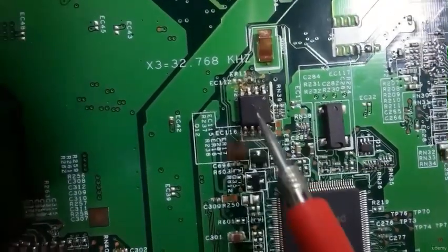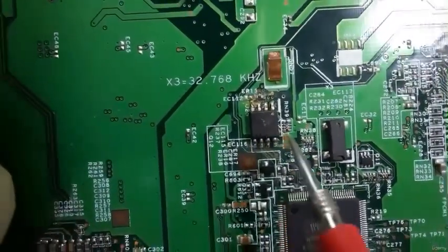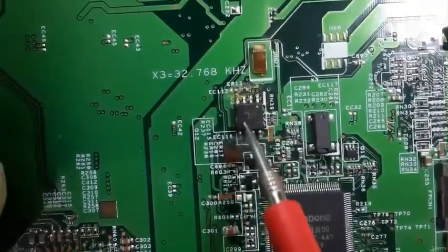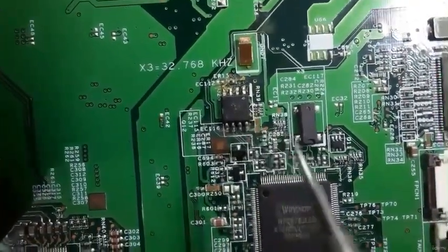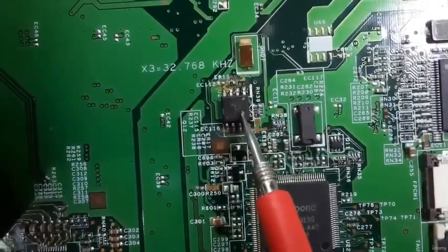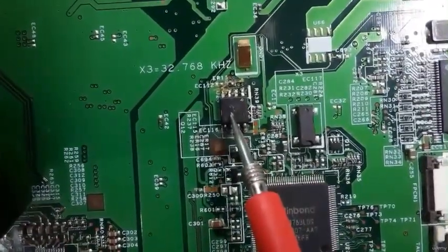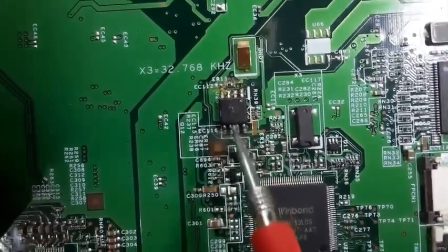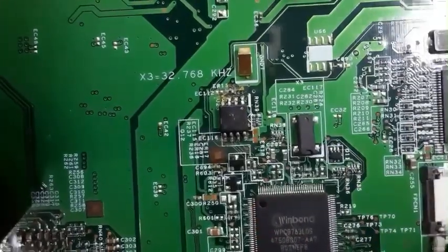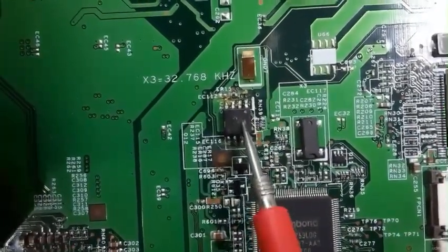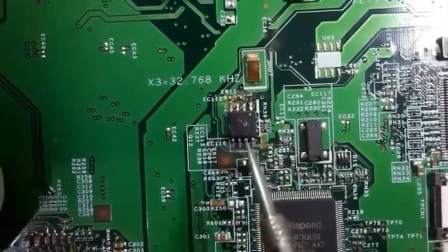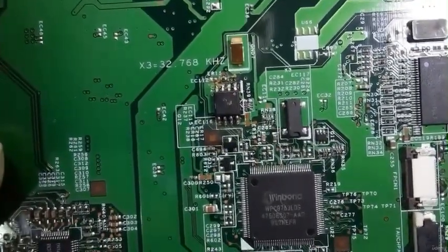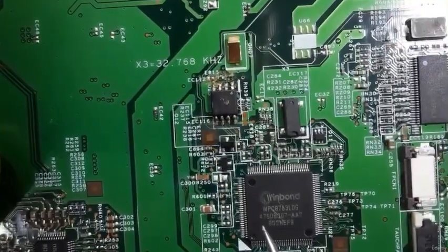This BIOS was already replaced, so it became bad again. Maybe we have to flash or reprogram the BIOS again with its flash, or maybe the BIOS IC is bad. So this motherboard has a bad BIOS. This BIOS should be replaced, and then the problem will be resolved.